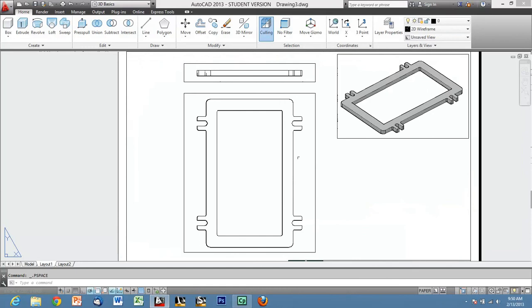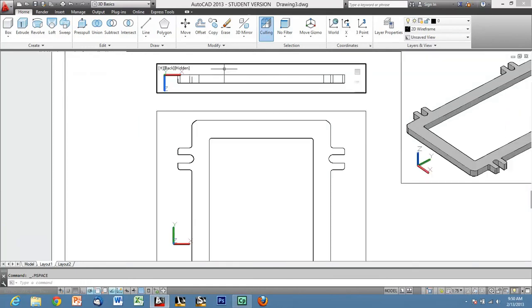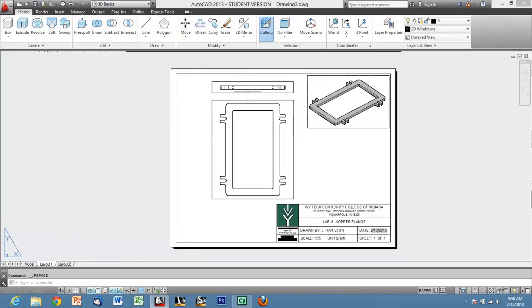And then for our viewport here, we want to set up these to have hidden lines. So remember, I'm going to double click inside this one. I'm going to type in VSOBSCUREDEDGES. I'm going to set that to be 1 to turn on. And you'll see my hidden lines show up right here, which is good. That's what we want. And I could do the same thing down here, but we know we're not really going to have any hidden edges, so it doesn't make much sense.